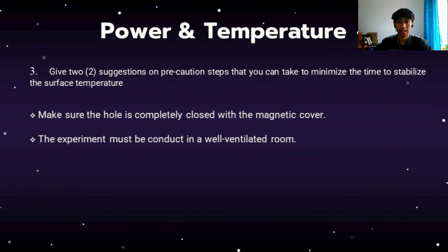So, two suggestions that we can take to minimize the time to stabilize the surface temperature. First, we need to make sure the hole on the side is completely closed with the magnetic cover. And lastly, it must be conducted in a well ventilated room.